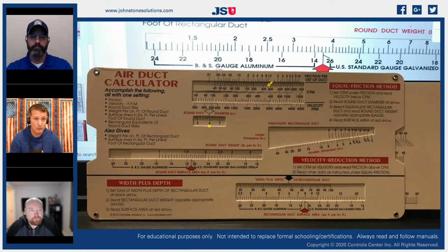I have a lot of noise. And I have a lot of pressure on my blower motor. My amps are going to be going up on my motor. My heat is going to be going up on a motor. And out of the experience that we're seeing, even with our ECM variable speeds, the best motors in our industry right now, 3-phase motors that are fully modulated, above 0.8 inches, these motors start overheating and they start freaking out, and they will shut themselves down and protect themselves.